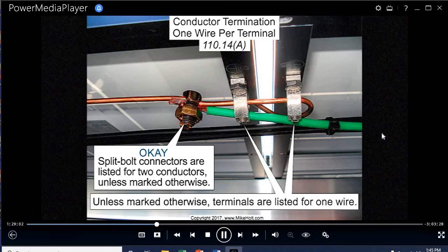And then if that is the case, this looks like a 6 gauge wire. And then I would have to show that this is a violation of 110.3(B), right? And then I should not even use this graphic in my book because I'm just now explaining, but this is a 110.3(B) standard saying that you cannot use 6 gauge and larger solid. It's definitely a number 8. So this is a number 8. Absolutely. Okay, exactly. That's the only way it would be permitted. And we're going to say it's an 8 gauge wire.